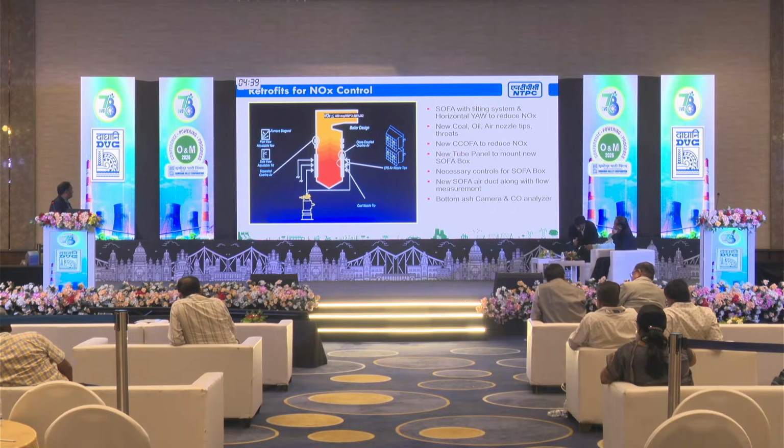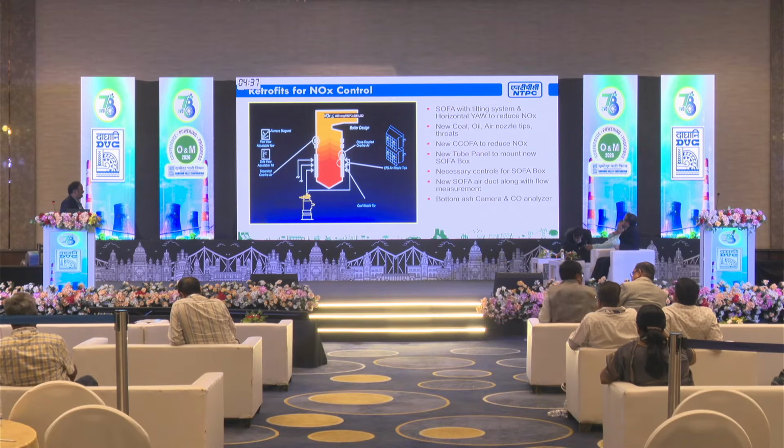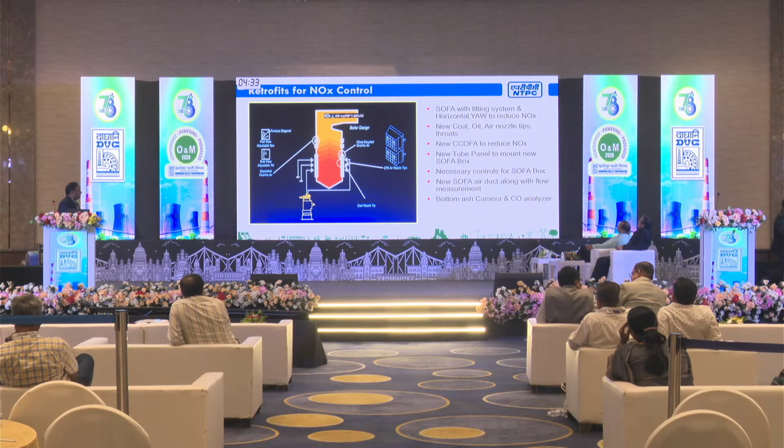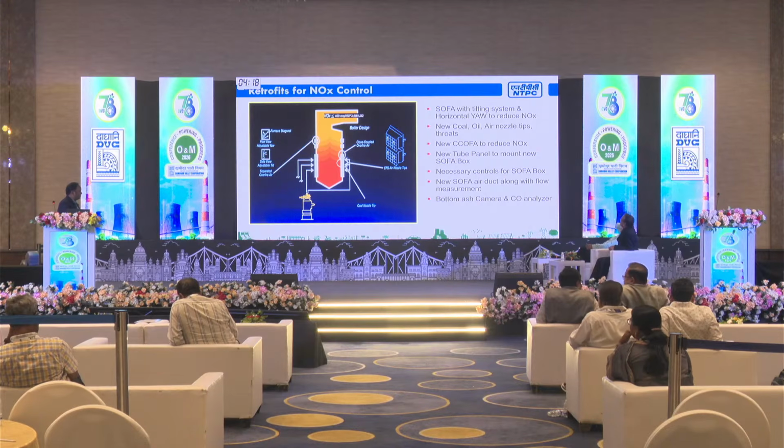NTPC has done modifications in around 50 to 52 units, like air staging or SOFA modification. It has provided low NOx burners and SOFA or CCOFA, for two-stage combustion.